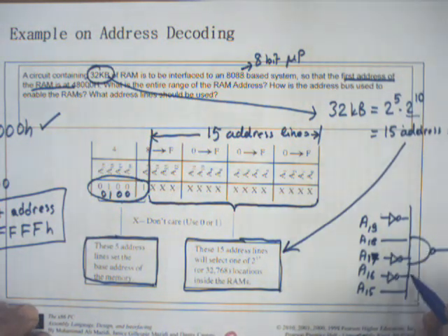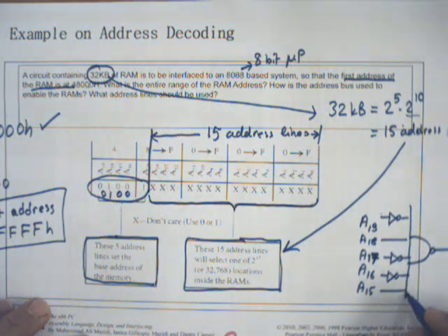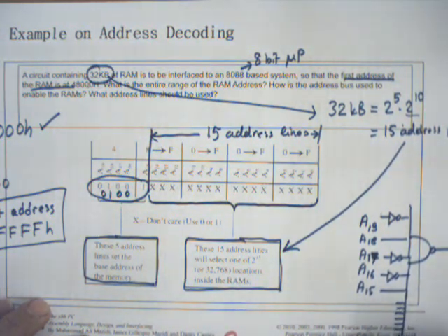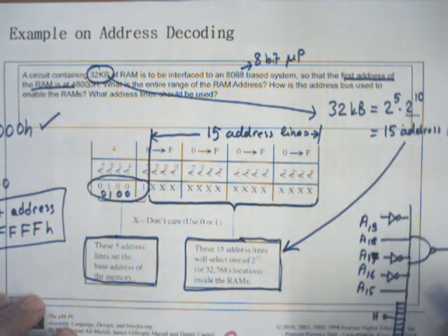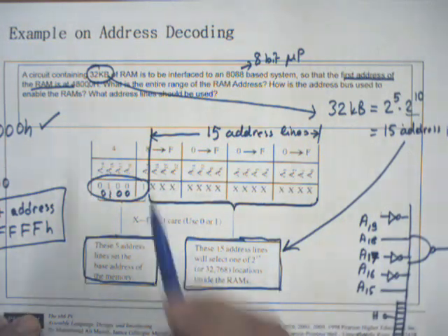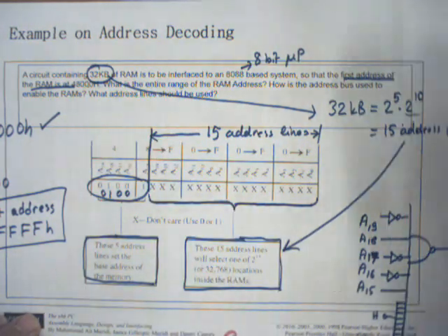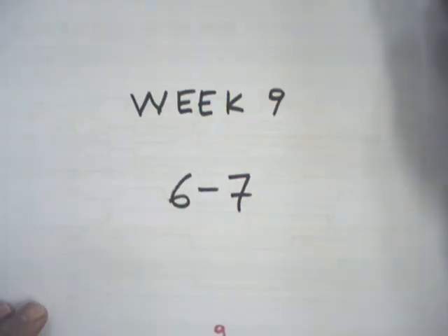And we have to use at least a 5-input NAND gate. There is no 5-input NAND gate in the market, so we can use a 13-input NAND gate with the 8 other inputs connected to high, for example, which does not change a thing in the logic. So this is a simple control logic circuit for this problem. I hope this is more understandable right now.